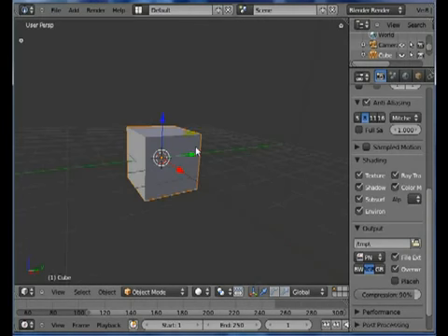If you've loaded pictures, for example, let's say I put a texture on this cube that is a picture of a brick wall. Well, if I don't pack the data in with this blend file, I'll take it to another machine and it won't know where to find that texture. It won't be available with my file. If I've added sounds for the game engine, they won't automatically go with the Blender file.